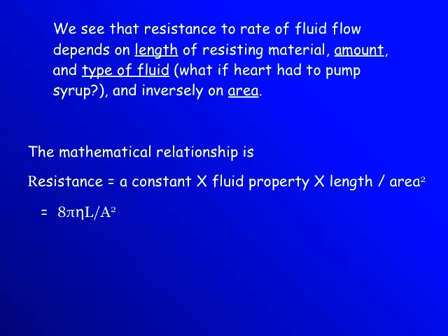So the mathematical relationship is resistance equals a constant times the fluid property, syrup, water, thick fluids, dense fluids, times the length of the tube divided by the area of the tube squared. So the area of the tube is very important.